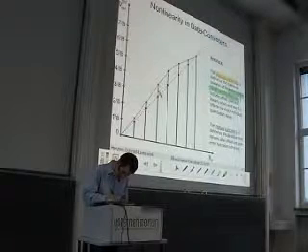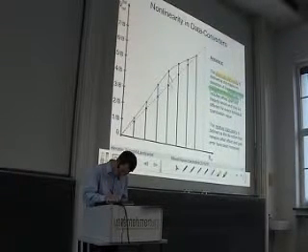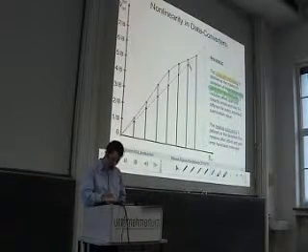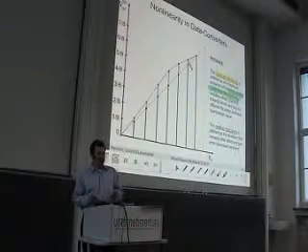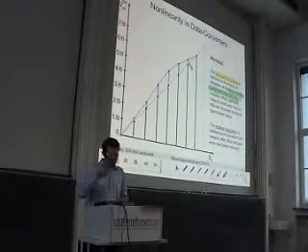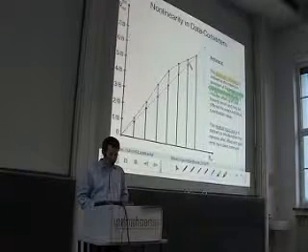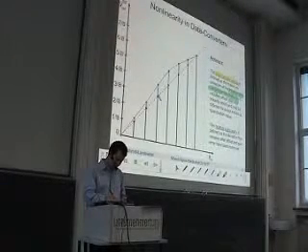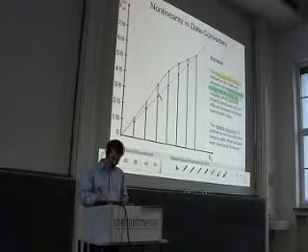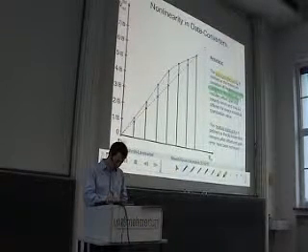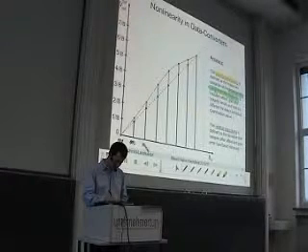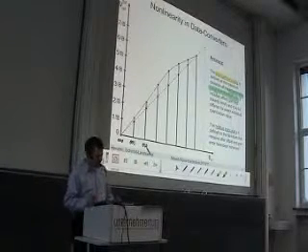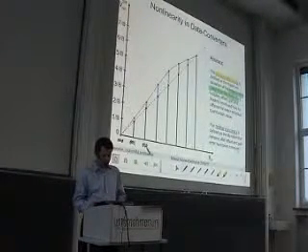So this is actually the absolute inaccuracy. If we want to give a single number as it is written in this definition, then we simply take the largest deviation. Or we can define this absolute inaccuracy for each point individually. So for each input value, for instance, 000, 001, 010, and so on, we get an absolute inaccuracy value.